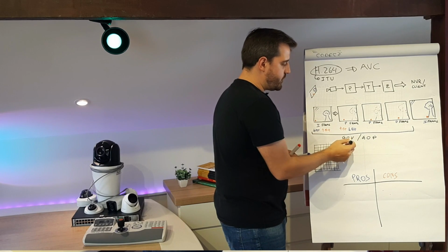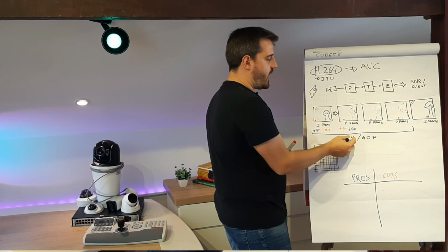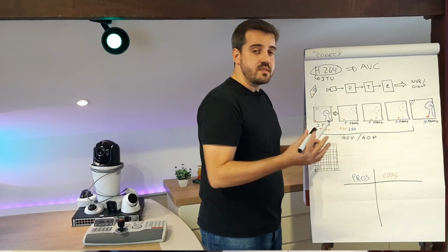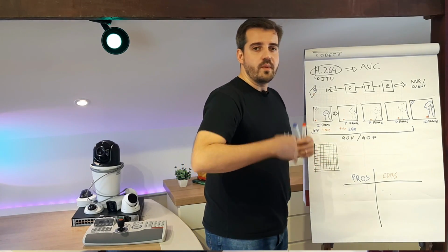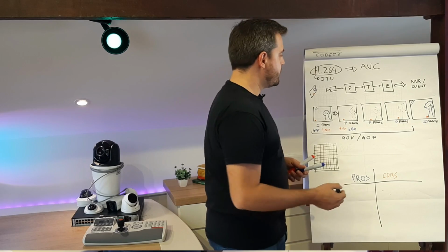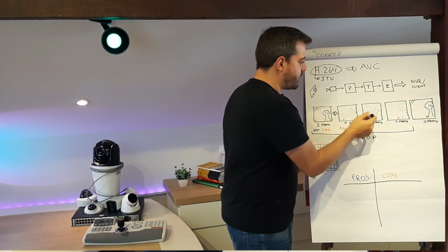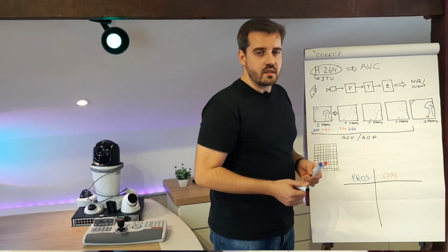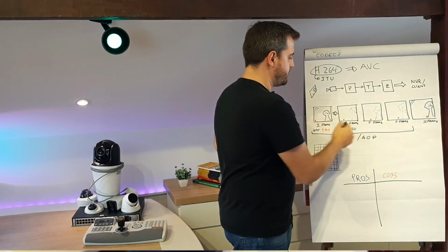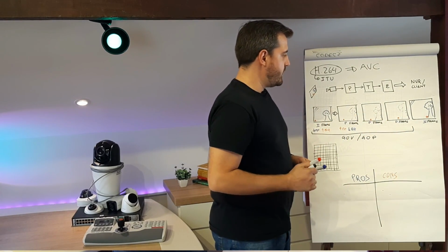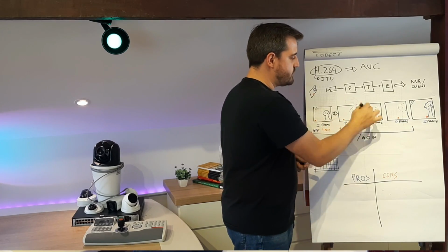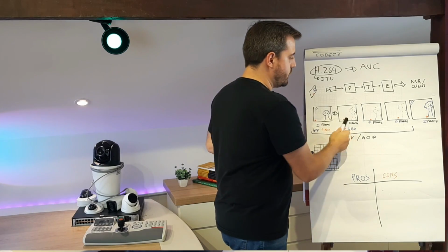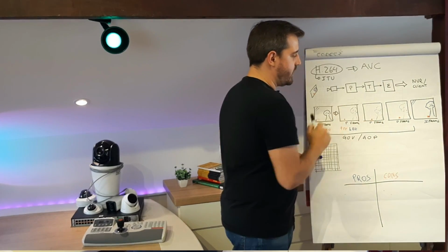So what happens if we set this value too high? Depending on the type of the scene, if it's a busy scene, a complex scene, with too many movements, etc., you can start to have deterioration after a few seconds, depending on the period that you are setting here. Because we're basically sending the differences, and it's predicting how the image will look with these new values.